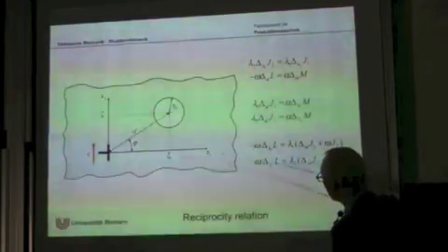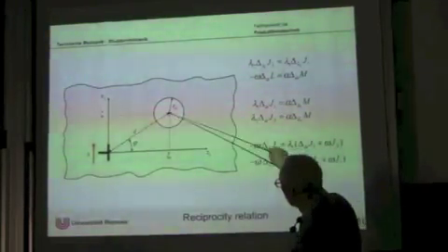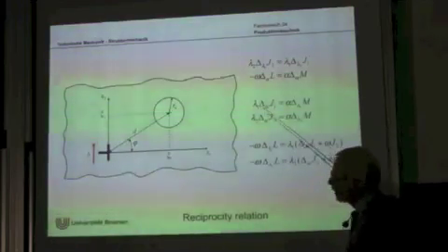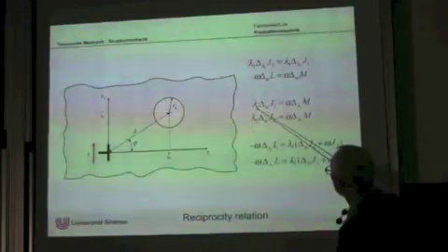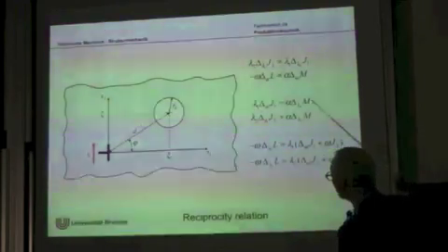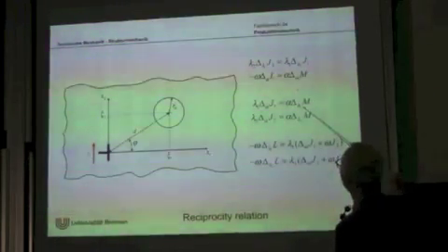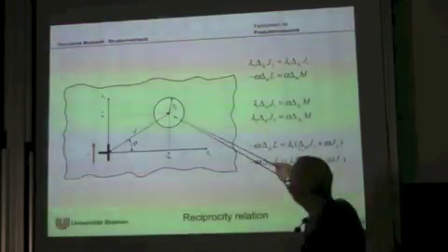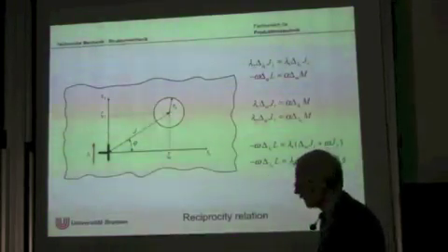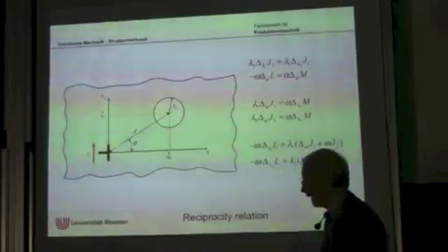The change of the J integral in this direction due to a self-similar expansion of the hole times this lambda 1 is equal to the change of the M integral due to a translation of the hole in lambda 1 direction times this self-similarity coefficient alpha.